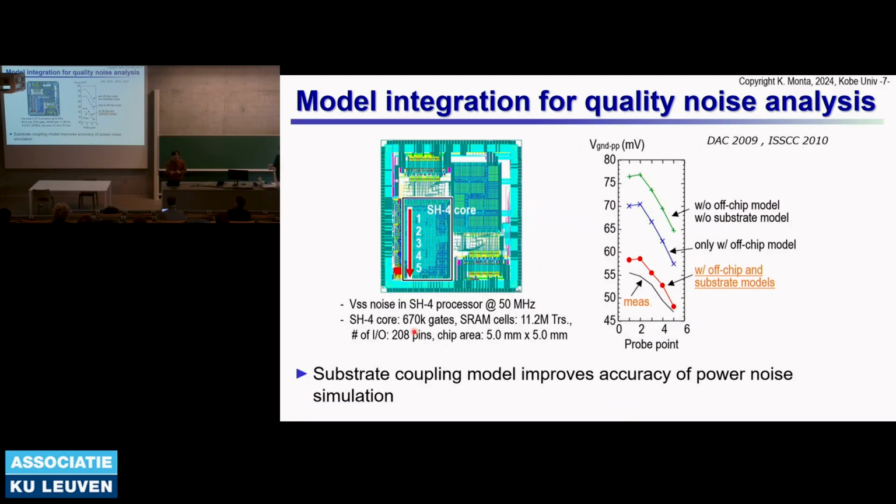How can we model these power supplies? You have millions of gates that will not be handled by SPICE. SPICE is limited to about 10,000 devices. That is quite a different level of integration from what you can handle with SPICE. So our technique, developed with an EDA vendor, the chip power model, CPM, can handle all the power consumption happening inside the microprocessor core. But accuracy was the key. How can we confirm the accuracy of the power models?